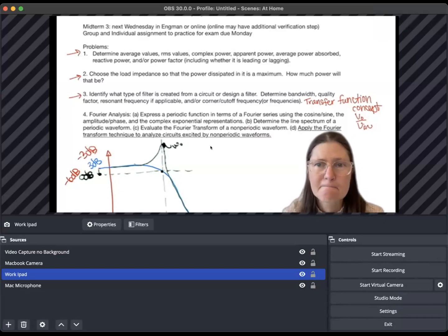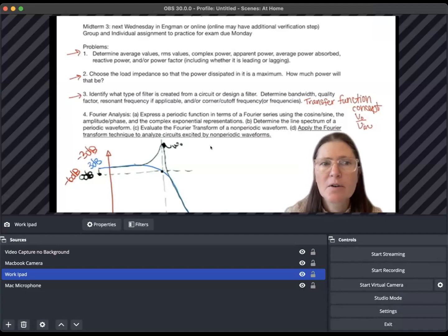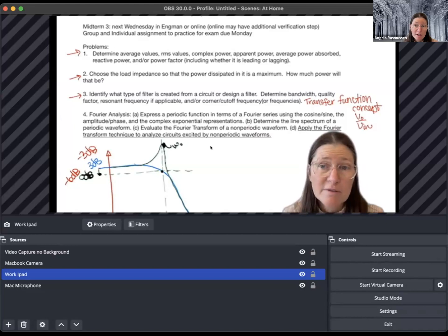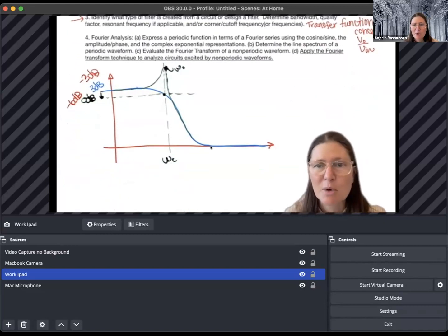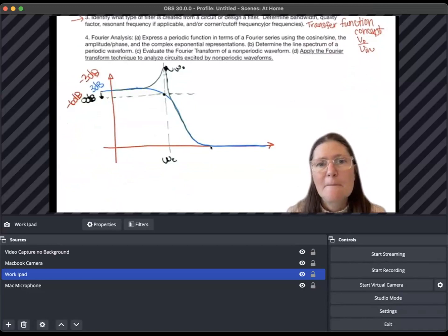Does that make sense? Will we have a value for V in eventually? Do we either solve for it or will it eventually be provided, or does it just stay as a variable? So for filters and amplifiers, you always leave it in a generic form. The reason is that you want to get this graph, the Bode plot graph. Therefore, you need a variable for it.